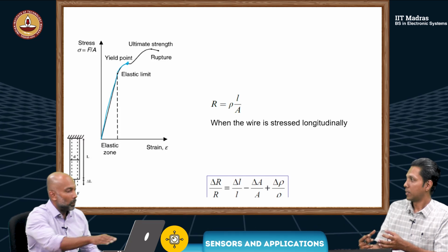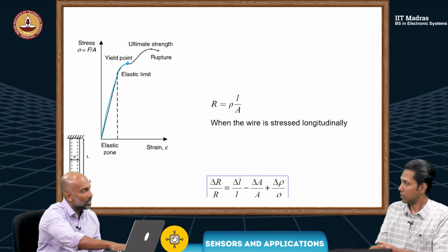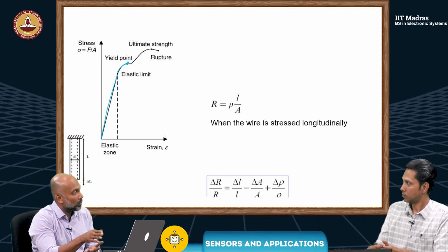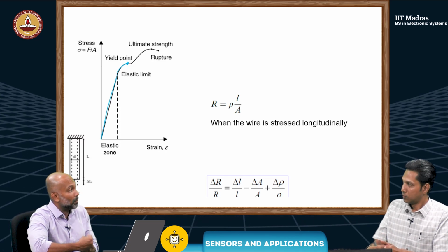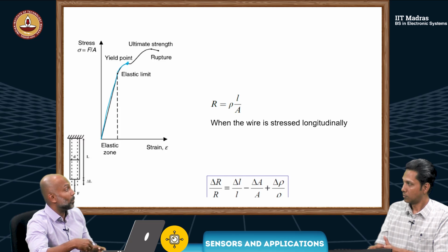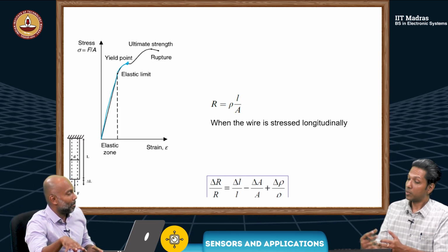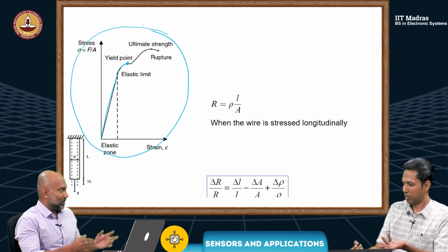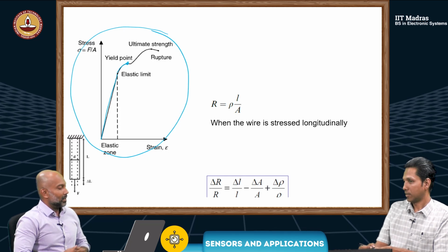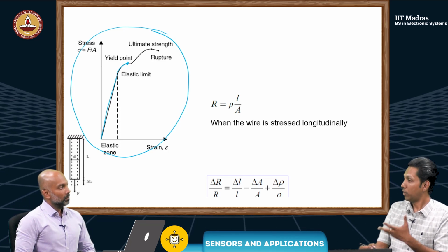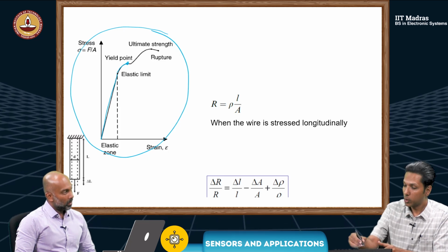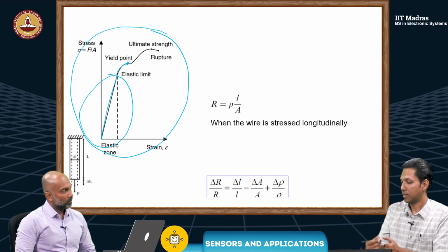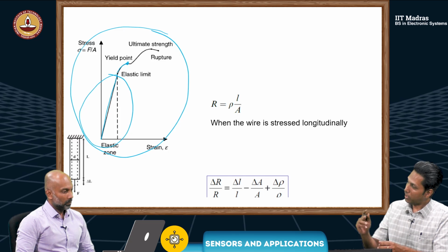When you look at the graph like this, do you first look at the material that's on it? Because if you're measuring something from the structure, we don't want that structure to break. This is actually a general characteristic of a metal while you're pulling it, so it is valid for both. When we design the resistive element, we will ensure that the stress seen by it is in this elastic zone. Same is valid for the other material.